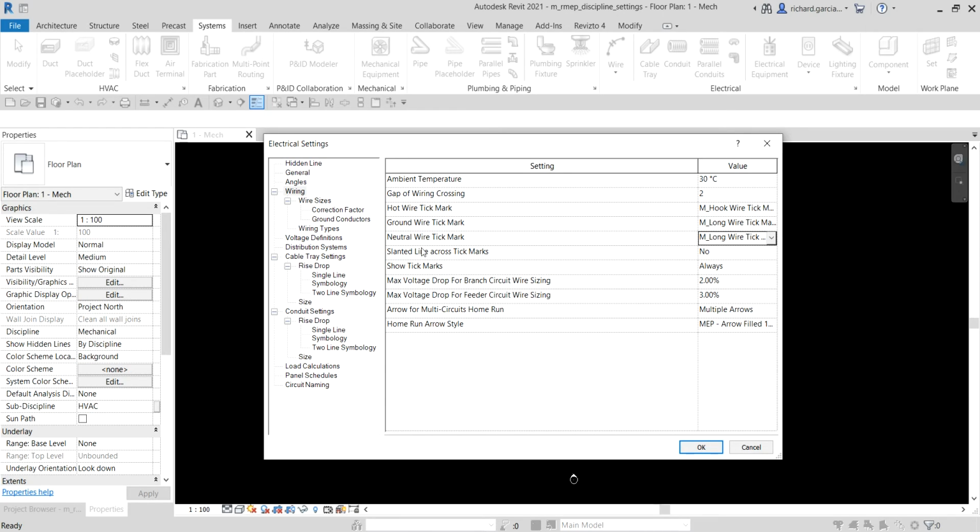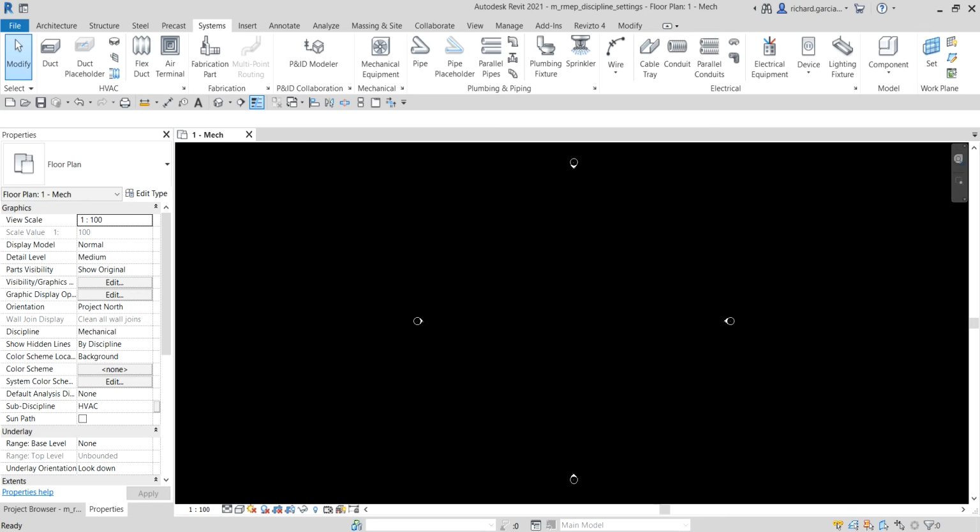And then there are other settings that you can also modify from here aside from that. So I'm just giving you an example. Alright, now let's select OK. So basically these are the mechanical settings and electrical settings. Try to modify these when you are creating your project template. So you need to incorporate the mechanical and electrical settings into your project template so that it is consistent. So every time you create a project, you already have the MS and ES settings on that template.